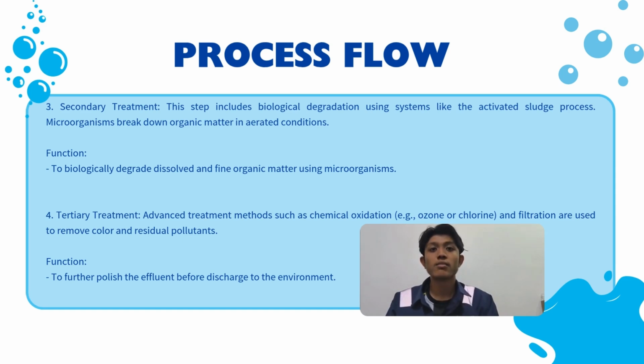Next, tertiary treatment. Advanced treatment methods such as chemical oxidation and filtration are used to remove color and residual pollutants. The function is to further polish the effluent before discharge to the environment.